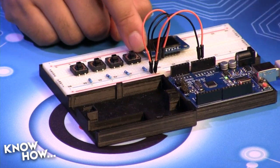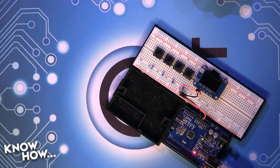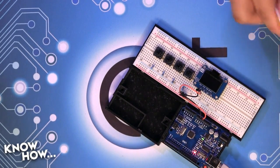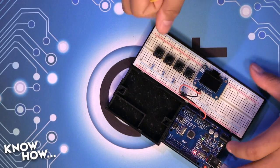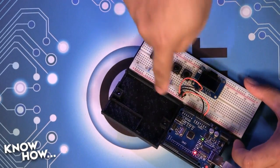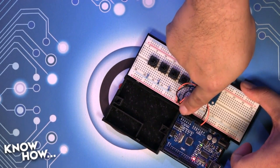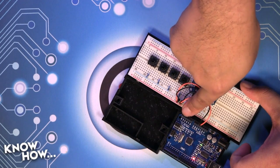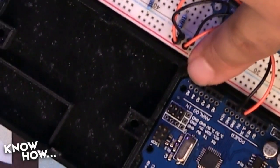All right. So we've got power and ground coming from the Arduino. The next thing I need to do is take my SCL and my SDA, my clock and my data lines. Now, on an Arduino Uno and a Nano, there should be 2. A4 is going to be my data. Okay. A5 is going to be my clock. So that's SDA, that's SCL. Okay. All right, so right there, 4 and 5.